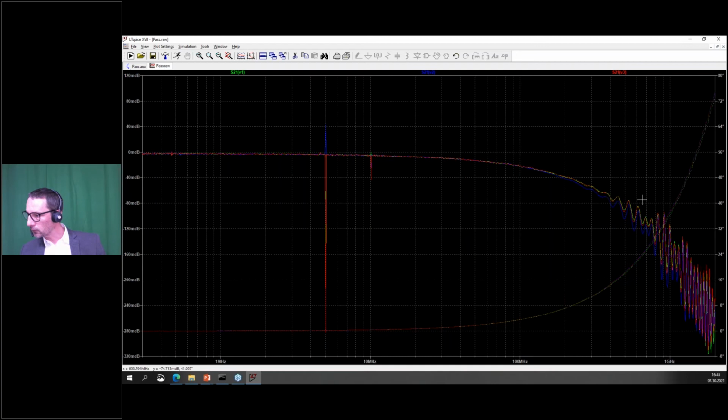Oh, sorry, that was at 100 megahertz. So we are roughly here at 1 gigahertz, so we are at minus 160 milli-dB. So overall, the biggest loss we have up here is minus 320 milli-dB at 2 gigahertz. So that's basically what's coming out, and we can see they are aligned quite nicely.